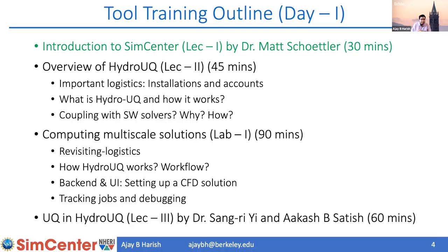So if I were to put crudely what UQ would be, let's say steel property, Young's modulus, is 210 GPa. But it's not always 210 GPa, it's always plus or minus something. So how does this plus or minus affect the overall structural response? Steel is just one material property, one example, but there can be several things. For example, when we take the fluid, if there is debris in the fluid, that can change the viscous properties of the fluid and so on and so forth.